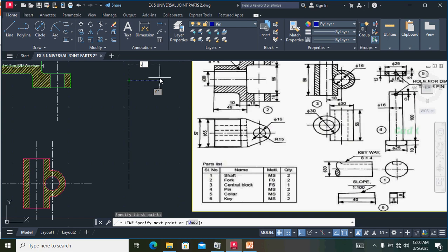Control reset. Now we want to select the line. From this point we have to draw the diameter 25, which means a distance of 12.5. Okay, then click enter. Then draw downward. The thickness of the head of the head bolt is 10 mm, so we provide 10.